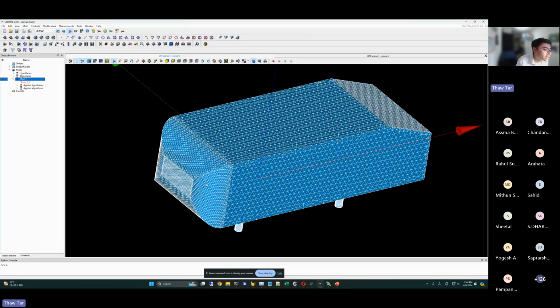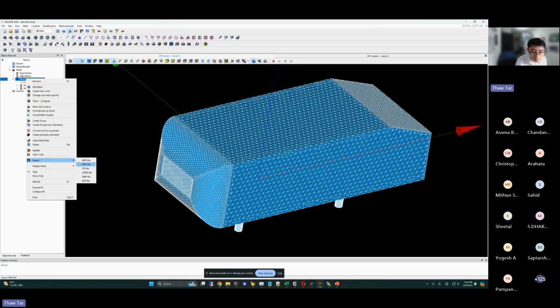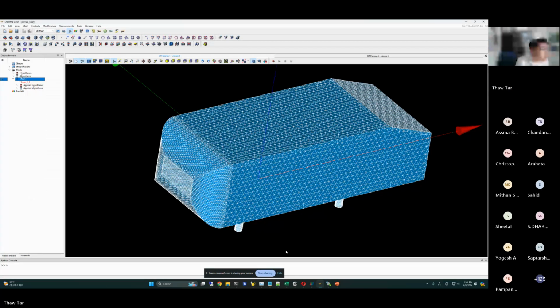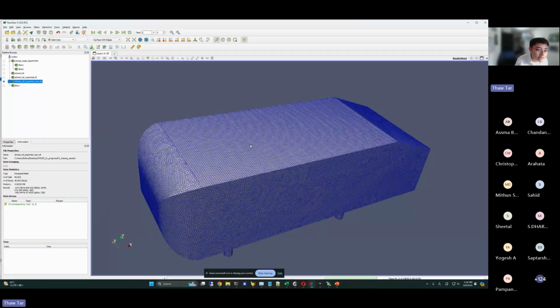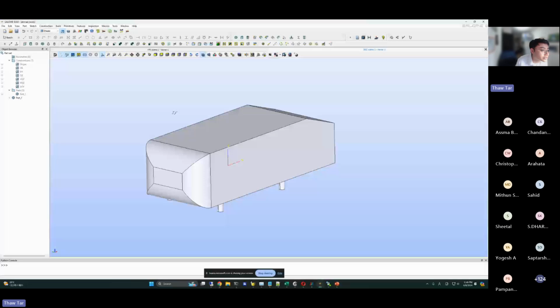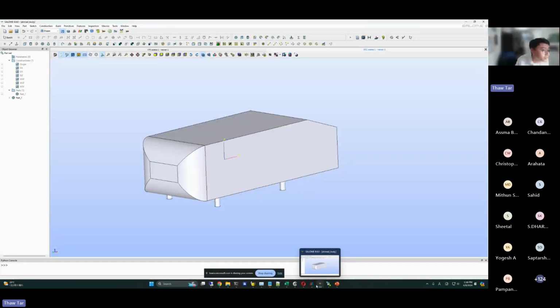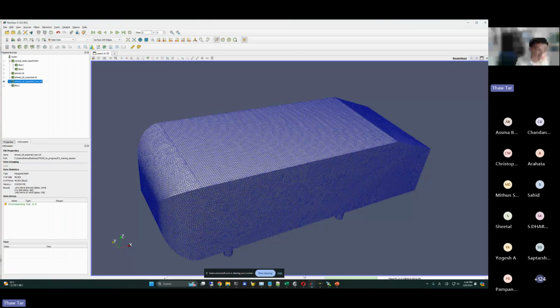And you can just export your STL mesh here, and I will not export. So your exported mesh should look like this, okay? But actually I will explain later. But your exported STL should look like this, okay? But if you export it from your CAD module, like here, there's an export option. Your STL will be like this, okay?